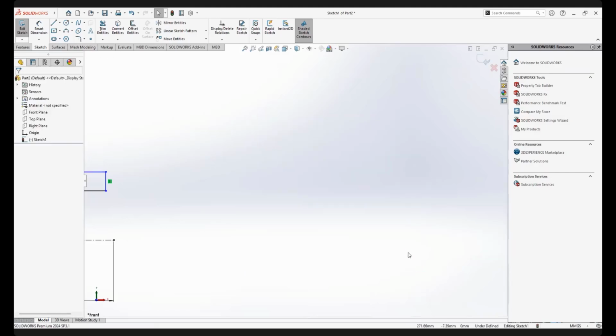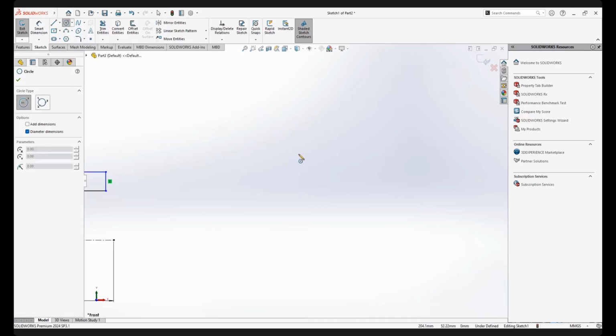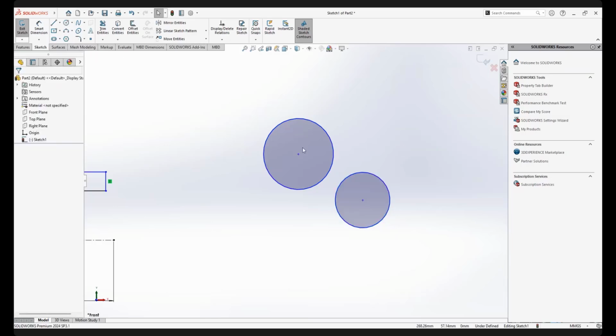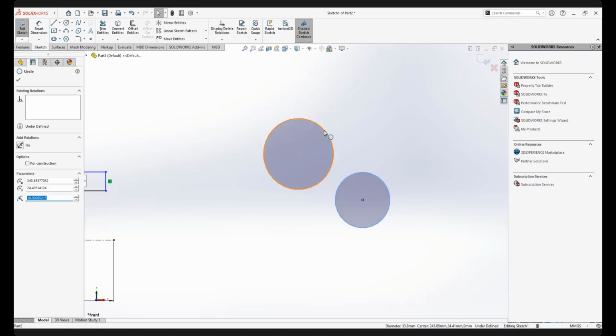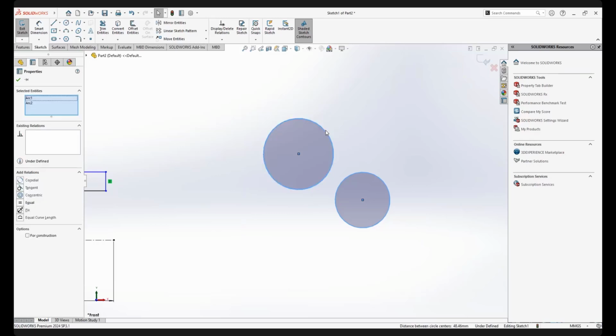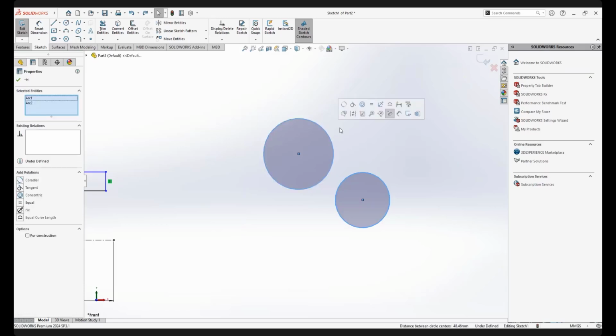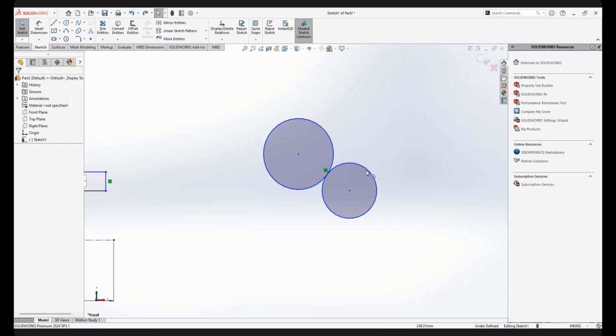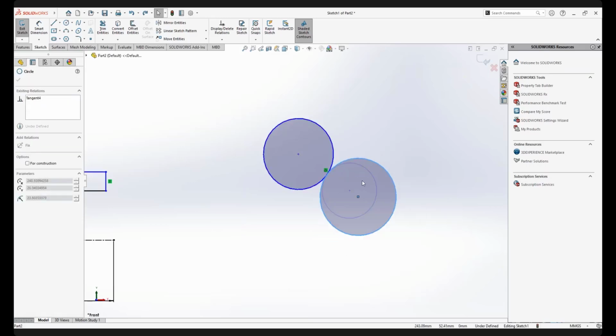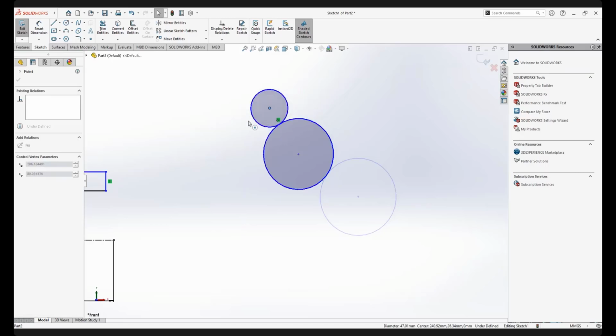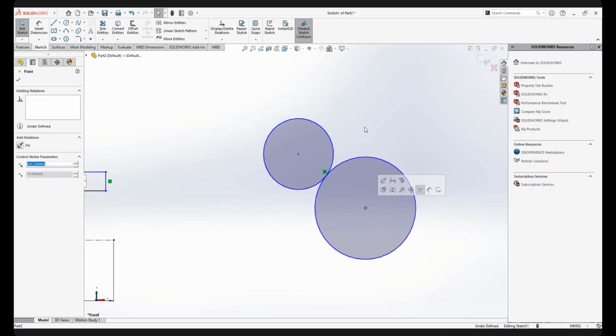There is another relation. Okay, one more thing is about a circular curve or a circle. I can select this. Select the circle. This one we can make coradial. Coradial means the same radius. Okay, undo. All right. This one and this one, we have another option, tangent. So it means the circle always touches tangent. If I move the circle or I move the center point, it always remains tangent. Understand me? Tangent to that second circle.